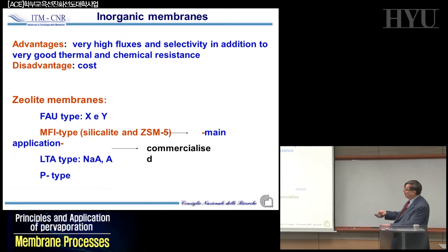I was mentioning inorganic membranes. You have the same case as Fuji, and you can have different kinds of zeolites that you can use. So that is still an area that today is starting again. We are working, for example, on zeolite membranes in the petrochemical industry for some separations, with a sponsor from the Middle East that needs to redesign their petrochemical production. There are hundreds or tens of different separations in which having one of these units working at an economic price is interesting. You can have a specific zeolite, you can have faujasite type, X and Y, you can have LTA, zeolite 1, zeolite 5, etc.